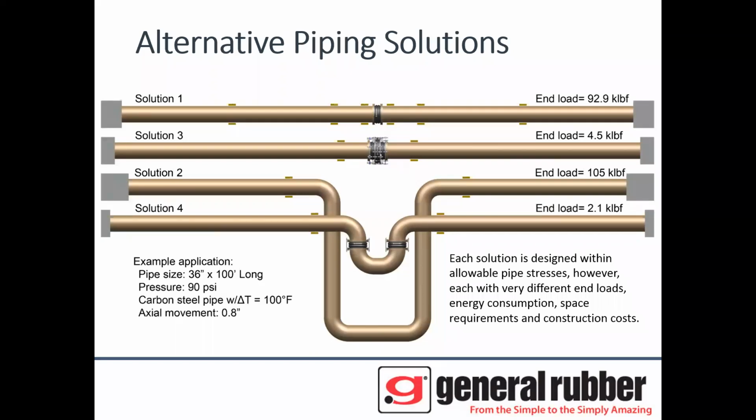Illustrating alternative piping solutions is another good way to make applications more clear. In this illustration, we have 4 examples of 36-inch diameter pipe. It's drawn to go over a 100-foot length. It operates at 90 psi and has an anticipated change in temperature of 100 degrees. So for this application, the piping is going to move 0.8 inches over that change in temperature, and there's nothing we can do about it. We have to design that as allowable movement.